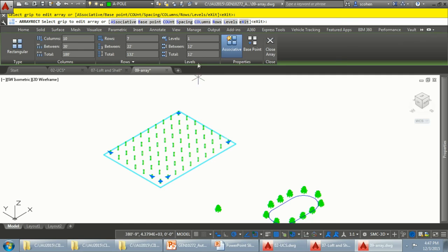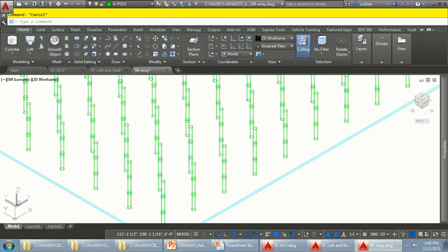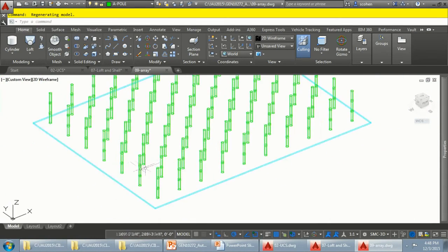Now here's a really cool thing. So with levels in this case, if I do a levels of 3, I get the height. So I don't have to redo stuff. And then, of course, for the distance I want between here, it should be 9 feet. And now I've got that. Again, pretty simple, and I'm done, basically. The only thing I have to do now is the floor.